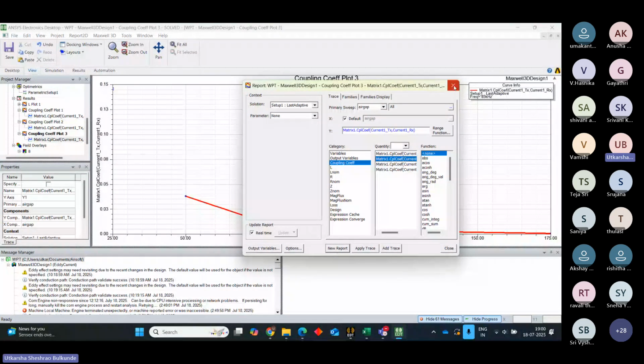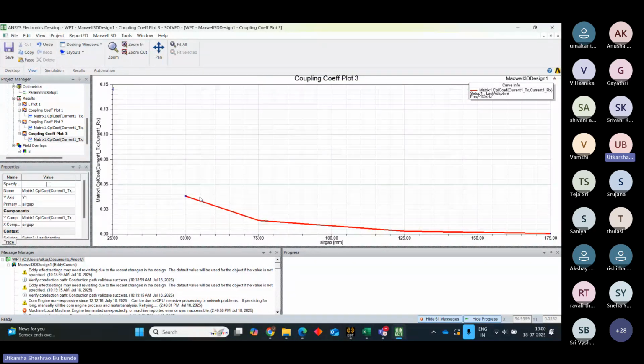No, it is not executed properly. So we will just see this, but remember this: when your coil dimension is too small, just keep the air gap accordingly so that you will get some coupling coefficient. Mostly around 0.2 is a good coupling coefficient in wireless power transfer.